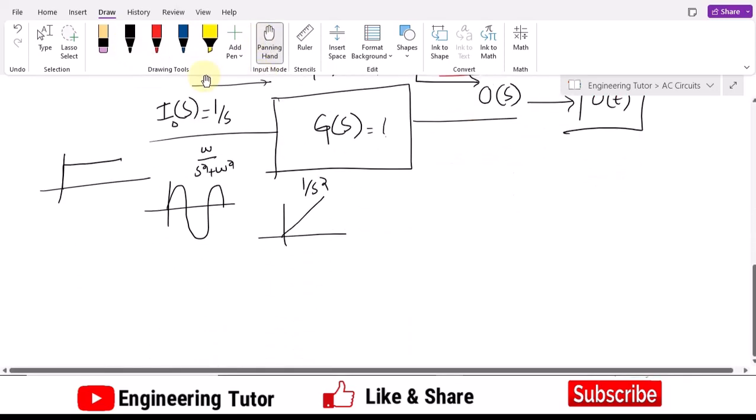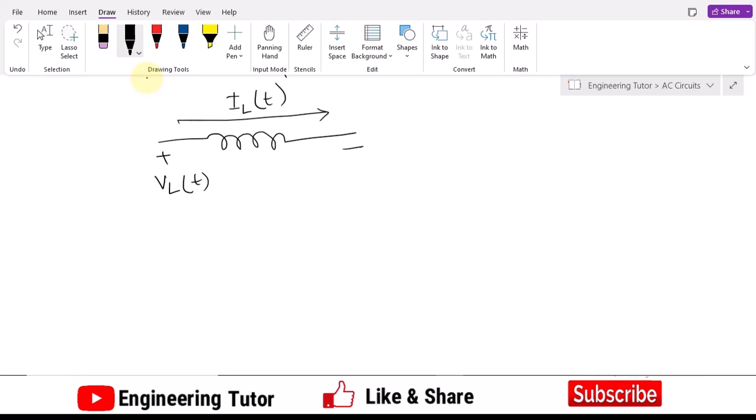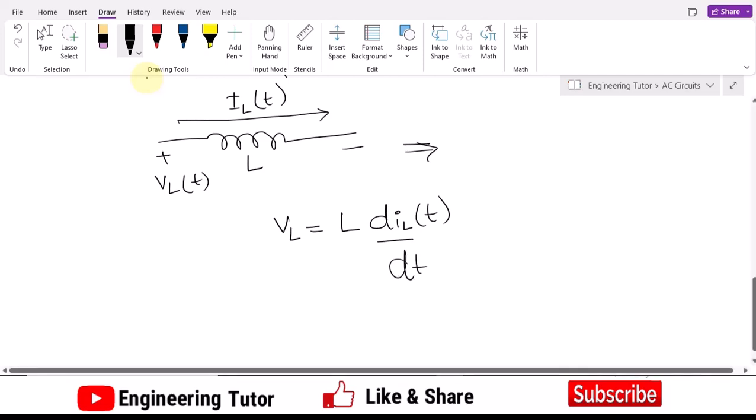Similarly, in order to see the effect of the Laplace transform on the inductor, consider an inductor with applied voltage plus minus V L of t, and the current flowing through it is I L of t, while the value of the inductor is L. So what will be the value of L in the S domain? We have recently seen that V L is equal to L times d I L of t divided by dt.